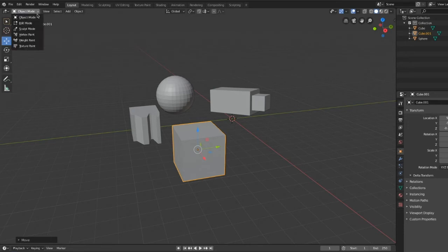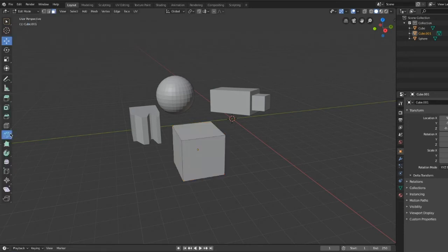Cool. I'm going to go into edit mode. And here is the knife tool, which is kind of interesting. These other tools that we've been using so far, the loop cut and offset loop cut, are pretty regimented, right? They're straight lines. The knife tool allows you to create the same polygonal viewports, but it can be all crazy. And when I'm finished, I'm going to hit return, and then I have these wackadoodle interfaces.